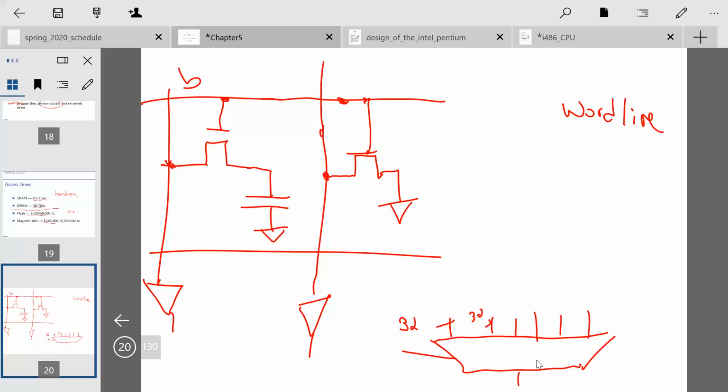They're single-ended though, and then we still have the multiplexer, which has the column decoder in it. Now, I left out the capacitor here. What's unique about DRAM is that over time there's leakage out of these capacitors through the pass transistor, and the capacitor also leaks through the dielectric because they're not perfect, so we have to do a continual refresh.